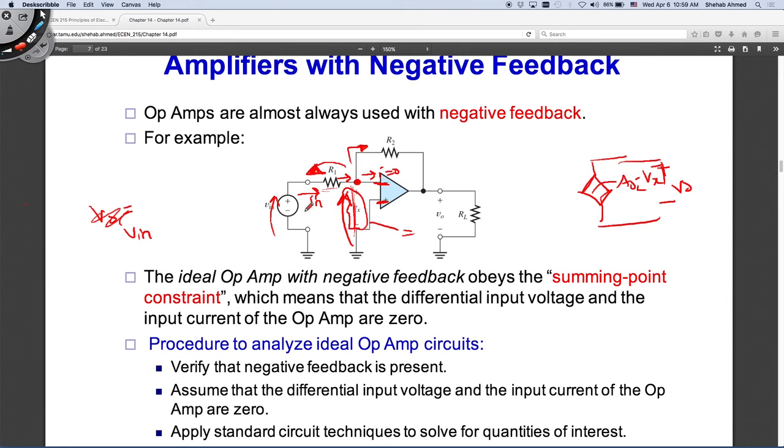here, this voltage is equal to I1 times this R1 plus Vx, this Vx here between these two terminals. If this Vx is 0 because of negative feedback, right? In general, it's not. Initially, if I remove this feedback, it's not 0. If I remove this feedback, it's equal to V in. Vx is equal to V in because it's the difference between the voltage at these two terminals.